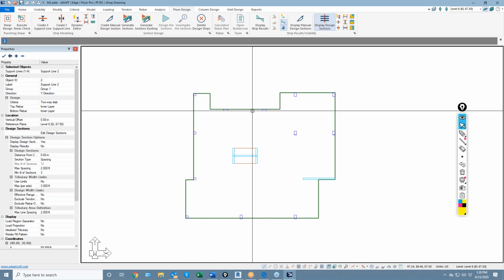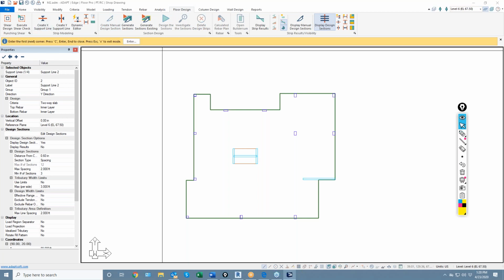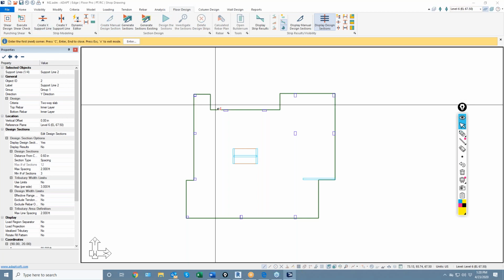They're not using any information that you've used for the other direction. So we're going to go ahead and add X strips. Now for the X strips, remember I don't necessarily have to be on an actual support when I generate the points on the support line. Remember, the banded tendons are really the supports for the uniform cables.